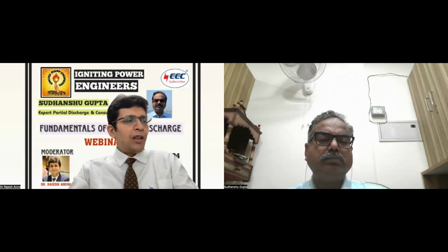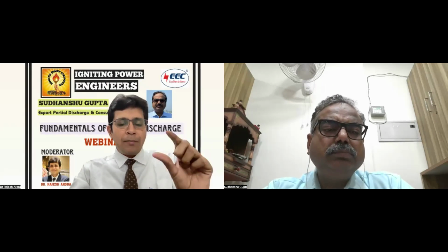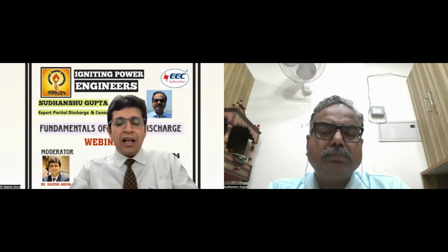When I say partial discharge, it is a kind of flashover of part of an insulation system, which is basically due to a localized electric field greater than the dielectric withstand capability of that particular part. However, the overall insulation system remains capable of withstanding the applied electric field. One important, crucial effect of this flashover is a high frequency pulse current that travels through the capacitance created by the entire insulation.